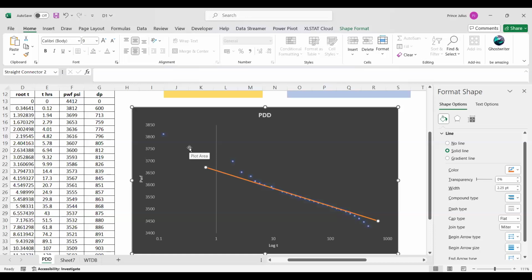So the damage part is there until you reach this point. Correspondingly, if you start putting a time scale, it may come around 7 or 8 hours. So until then, the damage is there. But what about the time for skin? That is up to 1 hour. But the wellbore effect might extend beyond skin. That may reach up to 8 hours. You can see if you project it down, you may reach around 6 or 7 hours or even 8 hours. Could be 7 or 8. So that much is the time where your wellbore has been affected with damage.